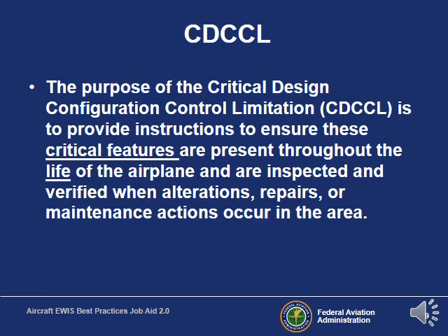So the CDCCL, the purpose is to provide instructions to ensure that the critical features are present throughout the life of the aircraft. The critical features are things like bonding resistance and separation of the wires. You want to make sure that there's no opportunity for any kind of spark to be created that could potentially cause the fuel system to ignite.